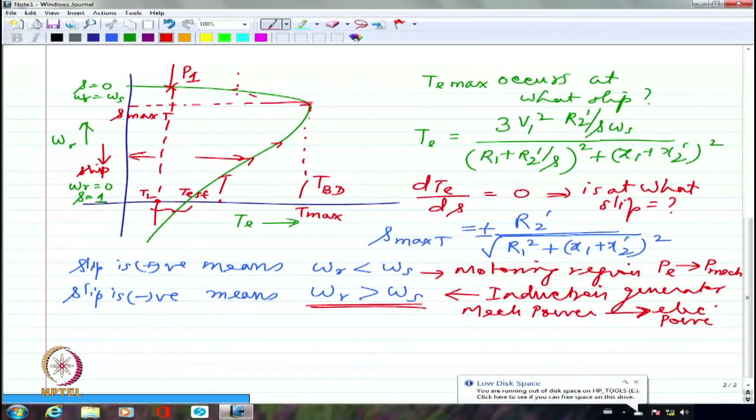It will just stall. It will say overload and wait. The elevator definitely will have an indicative button that it is overload, because the load torque is greater than whatever the machine is capable of generating at the starting condition. So that's a very good, very valid question.